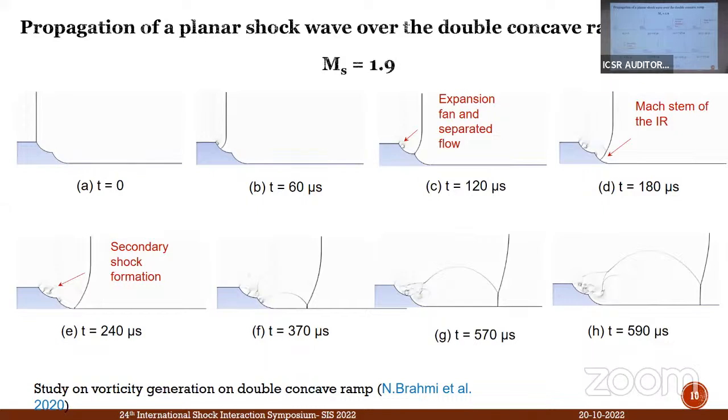Now, such a changed curvature shock moves over a plane surface. So that is our new concern. So this irregular reflection is being studied for transition. But I still see that the shape, everything seems to be the same as a single concave curve. The shock shape is all the same. No, sir. Actually, you can see here, it becomes an MR, I mean, a Mach reflection.